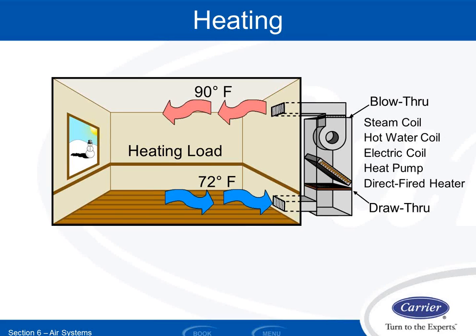The boiler will make that, and I will use a piping system and pumps to distribute the water to my coil, and then I'll run the hot air over the coil to heat the air up. So that's a fairly common mechanism. It's more common commercially, in large commercial buildings, than it is in light commercial or residential, but you can see it in all three building types.